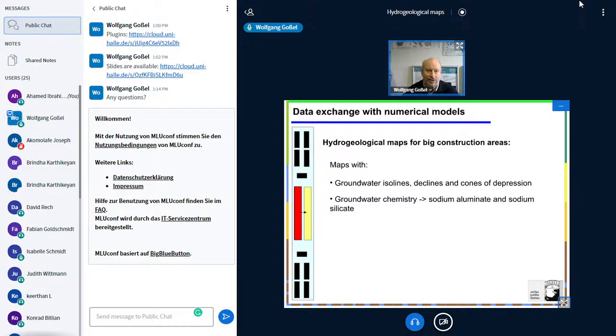a coverage deep in the groundwaters, in the saturated zone. They had to inject some chemistry, and this was at the beginning mostly sodium aluminate and sodium silicate. If you afterwards put some cement in it, then the pH will completely change, and sodium aluminate and sodium silicate are dissolved then, perhaps, and especially aluminates are very poisonous for trees. Therefore it was, or it is always, quite an interesting topic: the hydrochemistry, the groundwater levels, the path lines, where does the water come from, where does it go, also for construction areas. Yeah.